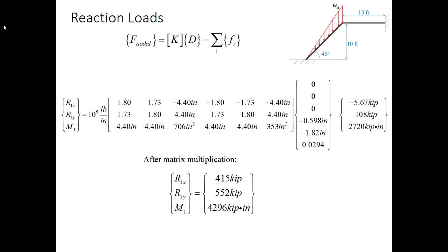So this shows you the full process of setting up, solving, and post-processing a frame element. As you can see, even though this is still a 1D element, this is starting to get pretty complicated, and this is why we are very thankful that we have computers to do FEA. We aren't doing all this by hand. This is about as far of complexity of hand calcs as I will do in this lecture series. Later on, we'll be talking about specific concepts, but we won't set up and solve full solution problems because it simply is too cumbersome for large numbers of degrees of freedom.